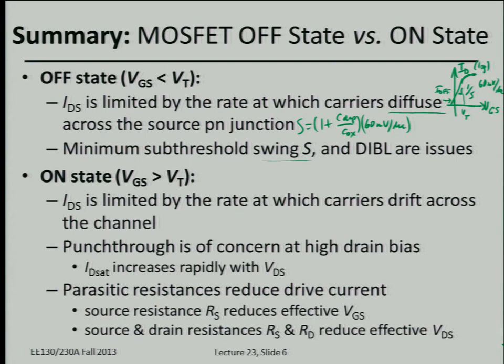Okay. So that's one requirement for a digital logic transistor: low off-state current, and it's important to have low off-state current when you have high drain to source voltage. So that's important to understand the application. Now in the on state, you'd like the circuit to operate quickly, so you'd like to have as high drive current as possible.